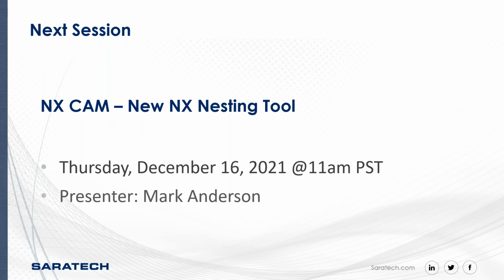Great. And the last question we have is, can I customize or automate Fibersim in any way? Yeah, this is another good one for power users. There are some capabilities to add custom reporting and some ability to export data from Fibersim and automate other processes outside of Fibersim. So for instance, if you wanted to generate a weight and balance report from Fibersim in a particular format that you could leverage in your other engineering tools, maybe it's even code that you have in Excel